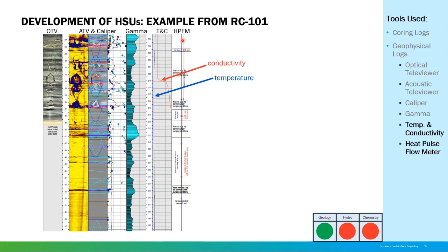We also, in the geophysical suite of tools, have the heat pulse flow meter, HPFM, up there on the image. And this essentially, you section off different lengths of the borehole and isolate them, and then use heat as a tracer to see if there's any flow vertically within that section. So again, looking at shorter sections and then really working to see if there's any flow within there.